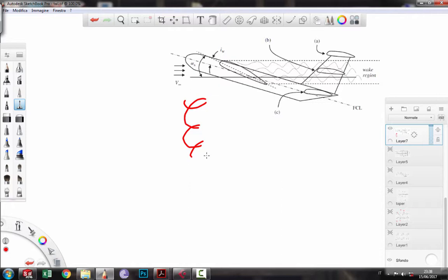The only surface on the aircraft that can recover it from a spin is the tail, not the horizontal but the rudder. Here the horizontal is blanketed by the wing wake. If we put it here or here, we will have some control, not during spin recovery, but some control during climbing, for example, because this is stalled. For spin recovery, remember that the rudder is the only surface that can recover the aircraft from the spin.